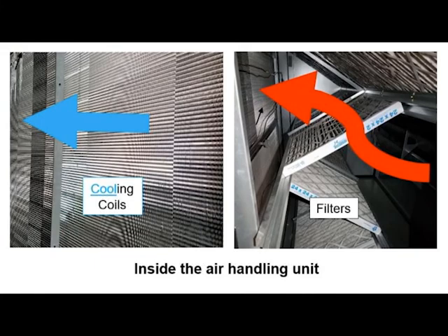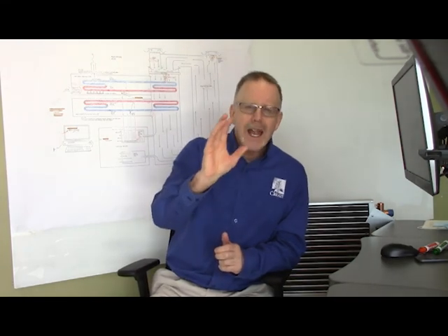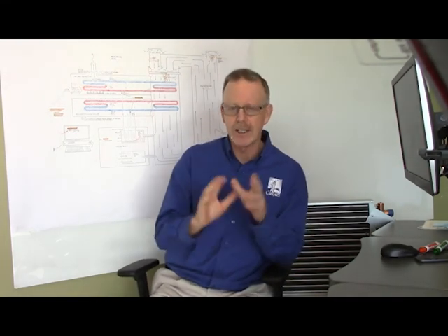The air conditioning heat exchanger, usually called a cooling coil, probably resembles the one for the boiler in the air handling system. But here, as warm air is forced through this coil, it is cooled and dehumidified. Then it's circulated throughout the building. Of course, the cold water in the coil is warmed in the process and is sent back outdoors to the chiller again. And what do you suppose happens to the air that's cooled and dehumidified in the air handler? Of course, it's used to cool the building. You might be sitting in a classroom being cooled just this way right now.